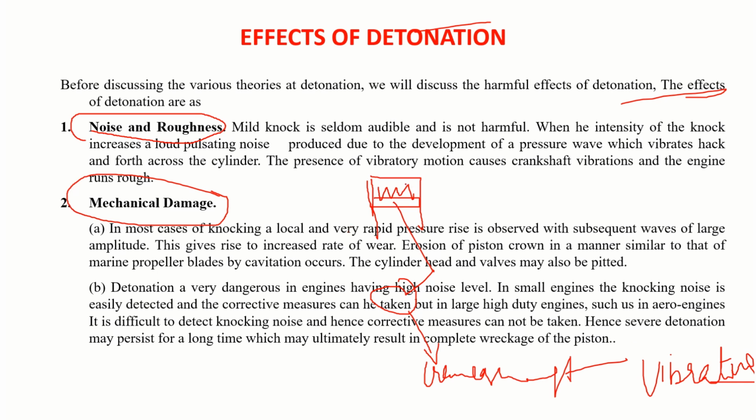Another thing is, you see here, there is a lot of temperature increase. There will be a temperature wave also. Whatever lubrication is here, that lubricant will be burnt out. And once the lubricant is not completely burnt, what will happen? It will leave some kind of carbon deposits.